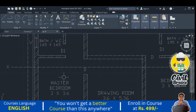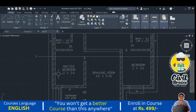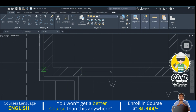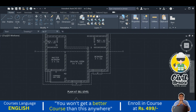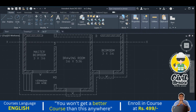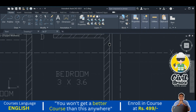So this center line of the wall, this center line, this center line, this center line. I just mark the center line first on the plan, then this line I just copy over here, and then easily I can do that. Okay, I just go to the section line. So how to mark the center line? I just go to the line, I just extend this line so that I can easily take the center line. One wall, this is our second wall, just extend this one. Third wall, and this one also,